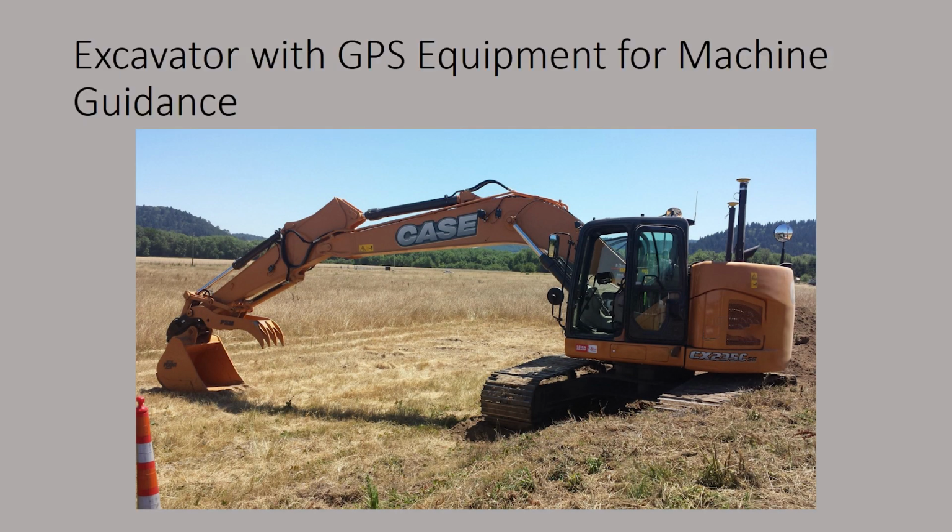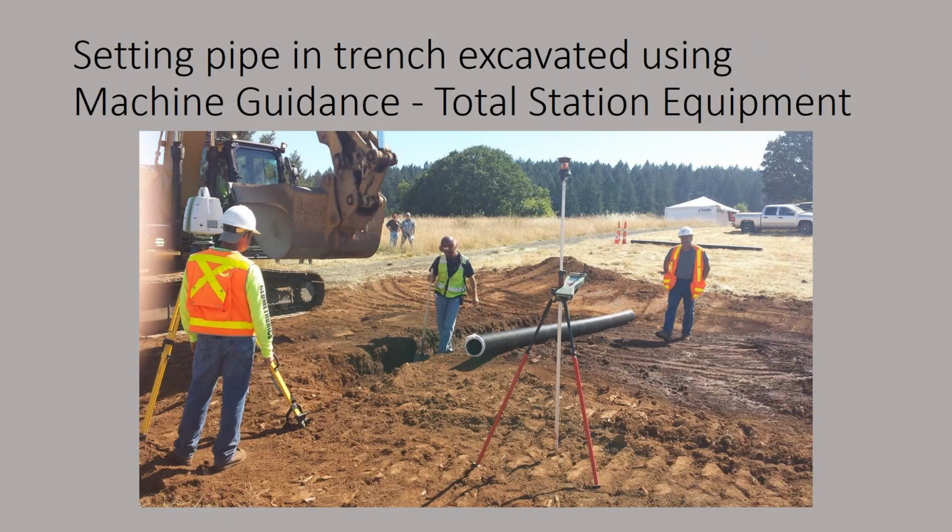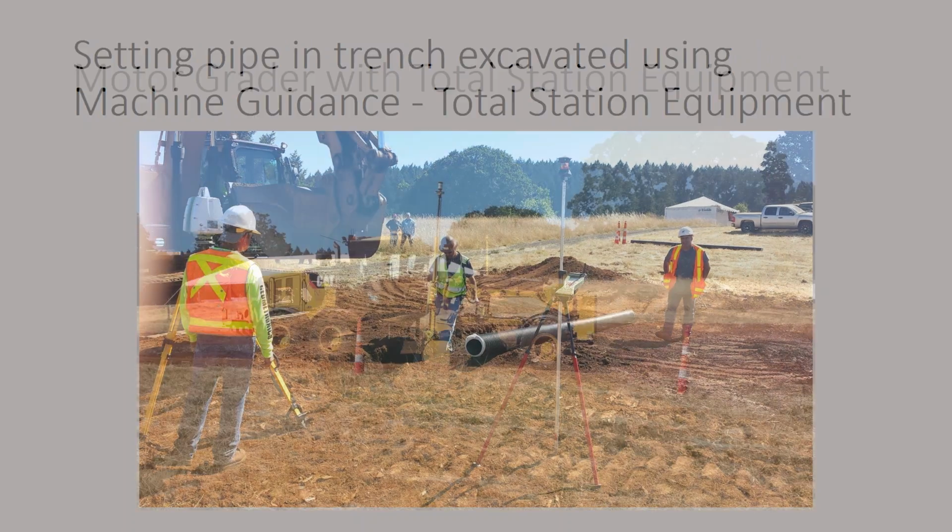This is a shot of just an excavator with some GPS equipment on top of it. And on this, they do some work with the hydraulics to figure out where the end of that bucket is, so they can look on the screen and see where they're digging. And that's more like using it in a passive sense. So they'll figure out where the bottom of that trench needs to be and dig that out just by looking at the screen and where their bucket is. Really minimize the surveying they have to do.